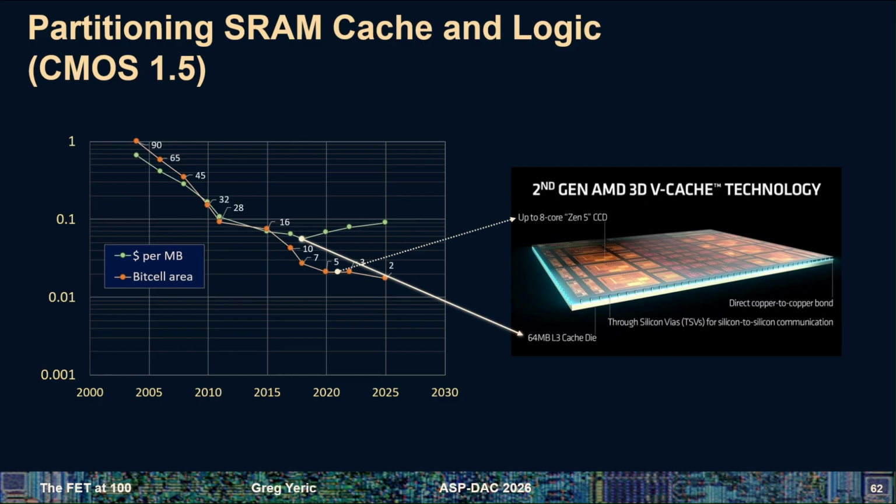And so memory, when you build in redundancy to the memory arrays, their yield is often 100% because you test it. You test each chip on the wafer, you find a few defects, you fix them with redundancy, and the chip now works. But if the cache memory is built into the logic and a piece of dust falls on the logic, then all the cache memory is 0 yield as well. So now by breaking this up into two pieces, the memory is now 100% yield where it was going to be 80%, just like the logic.